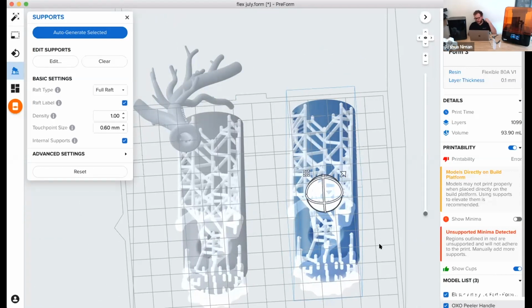The trick with going auto and then removing them is a function of how the software thinks, right? You as a human being can only place one support at a time. You look at a model and you place a support and then you think about how that's impacted the model and you place another support and you keep going like that, working your way up. At least I do. I work my way up from the base, that anchoring point of the model, all the way up to the top, and I place supports relative to each other after they've already had their influence on the part.